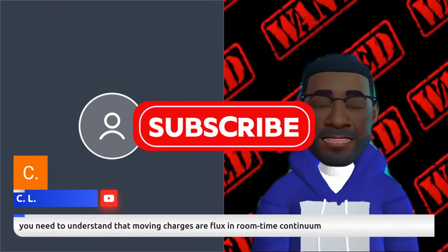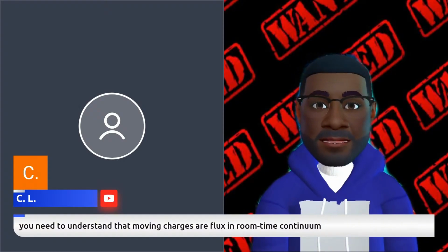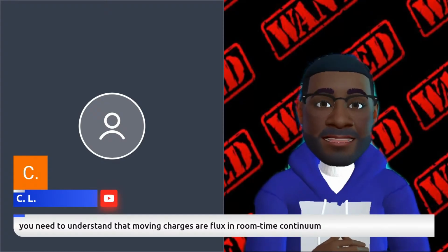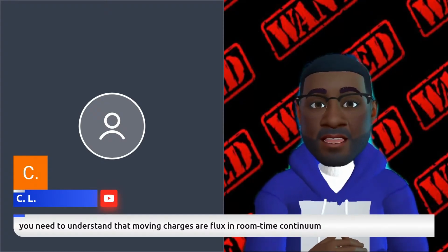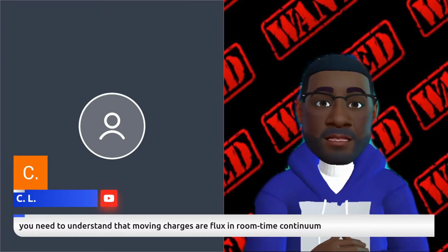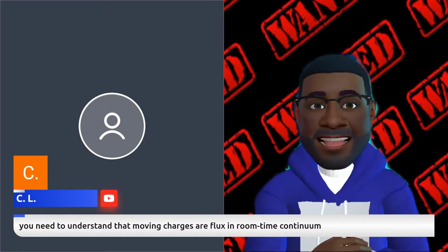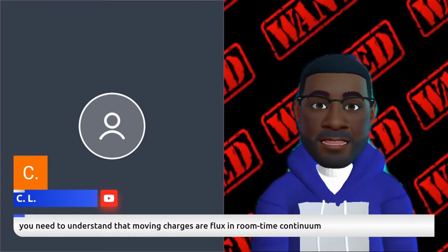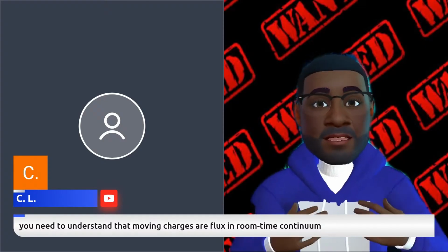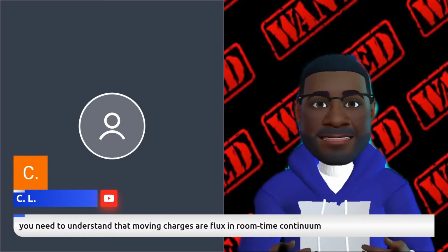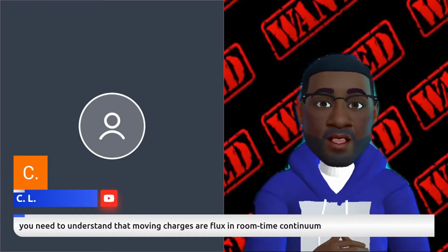The gate is a plate. So when you put a bias on it, charge carriers, which are minority charge carriers depending on the semiconductor, are attracted to that plate. They can only go to the plate or back to the substrate. The source and drain are perpendicular to that. The current flow is actually 90 degrees to that bias on the gate. So the gate is not creating current. It's creating the path. That's it. It does not provide current. It creates a path for the source and drain to electrically connect.